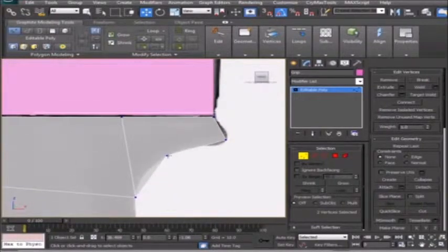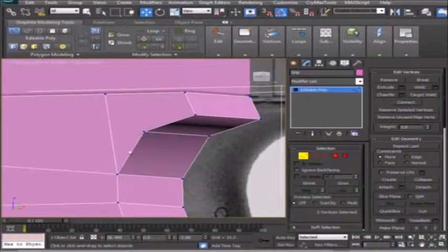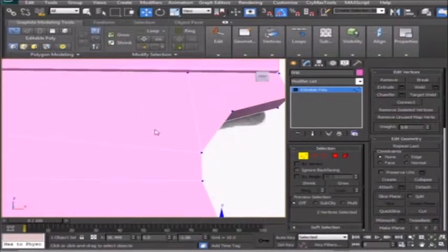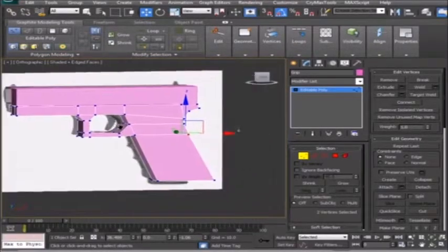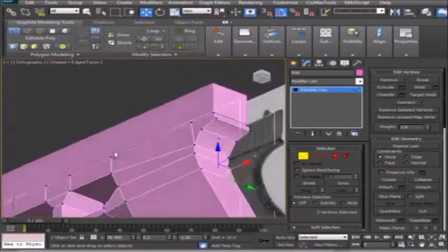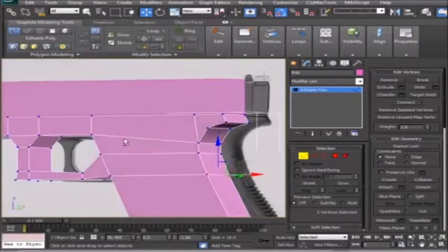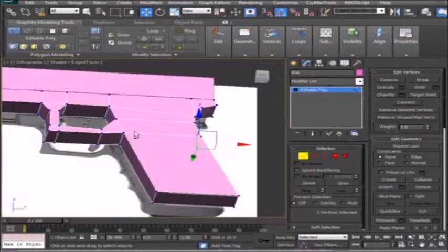You'll also notice that I broke the rule of quad. The Alt X here. I no longer have a quad here. Okay, I now have a 1, 2, 3, 4, 5-sided polygon. I am not going to be turbo smoothing this. I am not going to be sculpting anything on it, subdividing it in any fashion. So it is perfectly fine for me to break quads. I'm not worried about it.